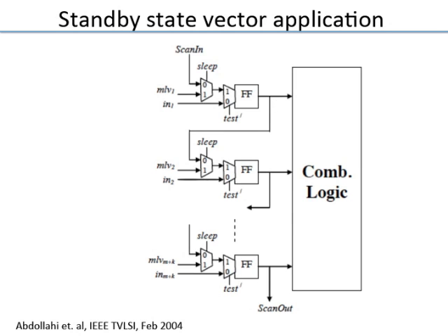So that's how it works: before you turn on the clock gating, one cycle before, you set this up. And this MLV1 till MLVM plus K are statically determined during design time. So this could be hard coded 0101, because once you have a particular combinational logic, there is a particular input vector which will give you the minimum leakage, so you just hard code it. Before I enter the standby state, before I shut off the clock, one cycle before, I apply this so that this value gets flopped in and presented here. Then I shut off the clock.